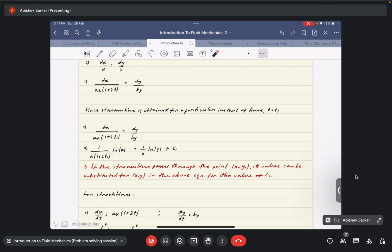Since all these terms are constant, we can now integrate them to get the equation of the streamline as 1 by (a into (1 plus 2t1)) ln x is equal to 1 by b ln y plus some constant c1.